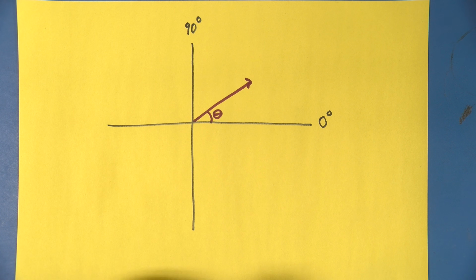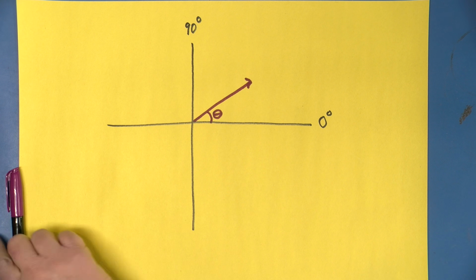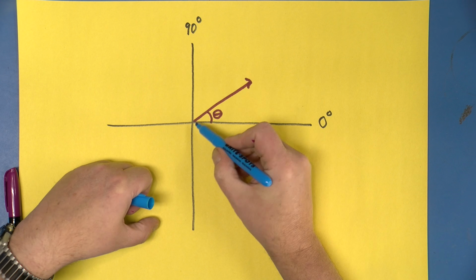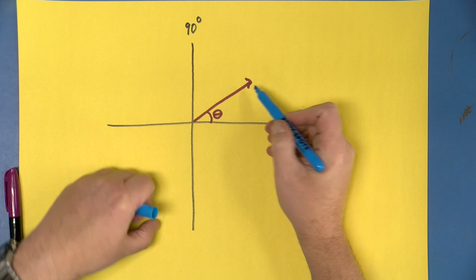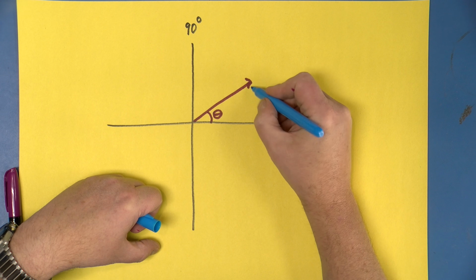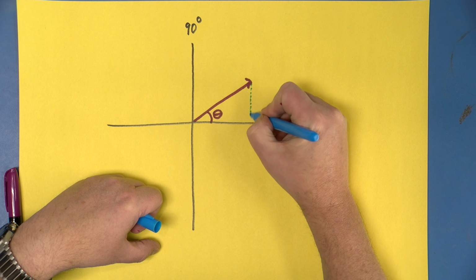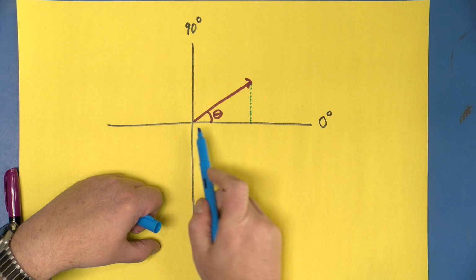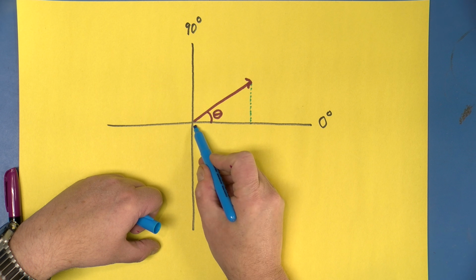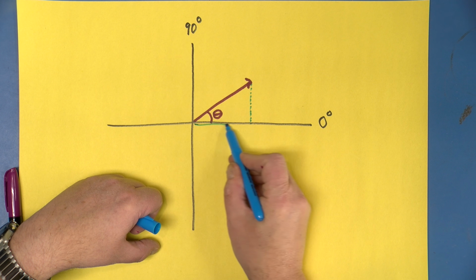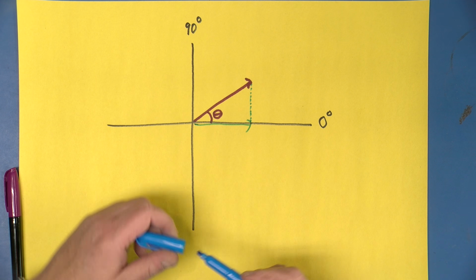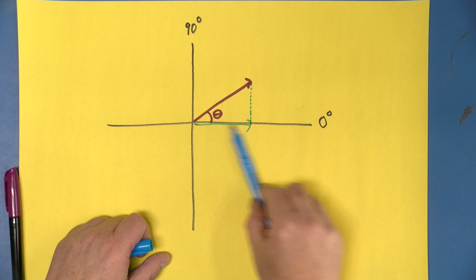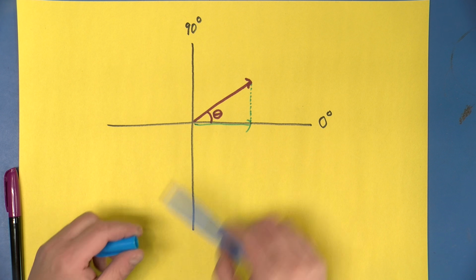So what might be of interest would be, if we have the total current, and this current you could measure with an ammeter if you just put it on a wire, how can we tell how much of that current is indeed the real part, the part that's delivering real power? And you might be looking at this and saying, wow, that forms a triangle with an angle.